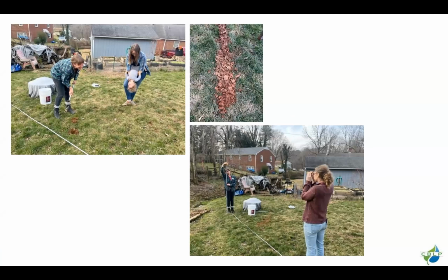Then the other things you might want to know during that site visit are the soils in the area. This is actually one of those sites where the Web Soil Survey said this property is too small for the soil map you're showing. That's an even better argument for taking a soil probe or soil auger and doing a quick check.